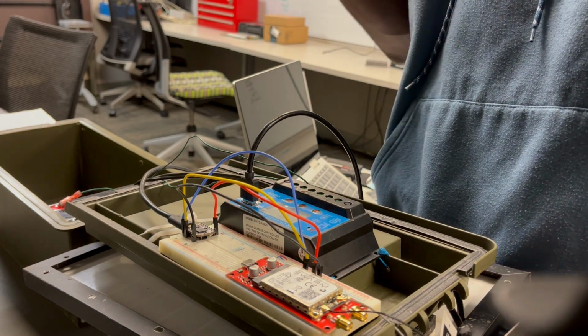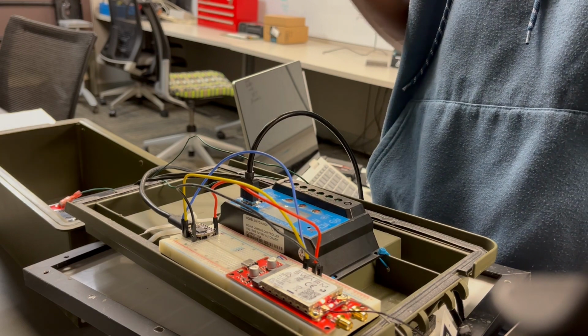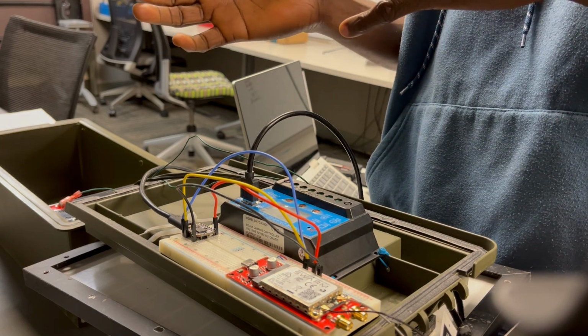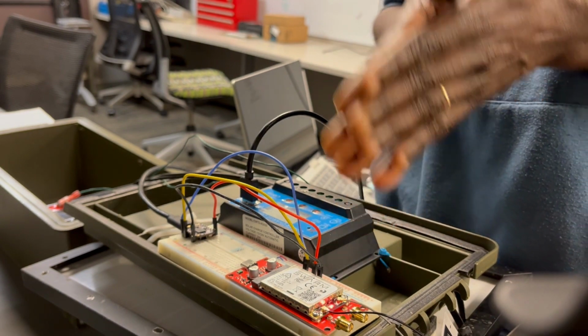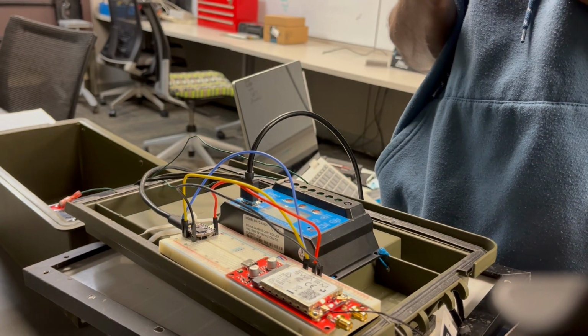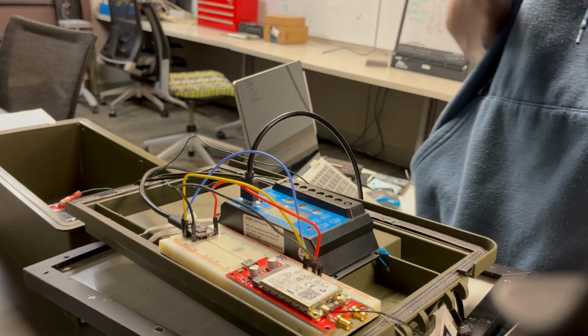Maybe you are in the lab environment. That is a scenario I have. So from the lab environment, how do you access the QT-PY and the Swarm board remotely? That is by making the QT-PY have a Wi-Fi connection, then setting it up as a web server.